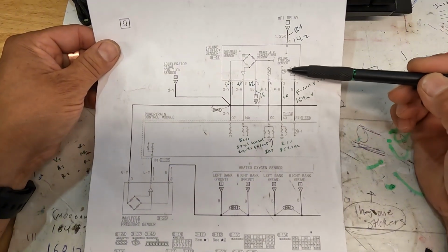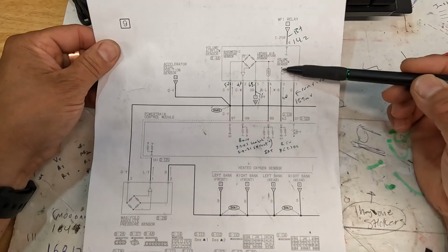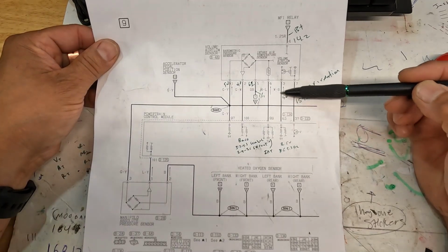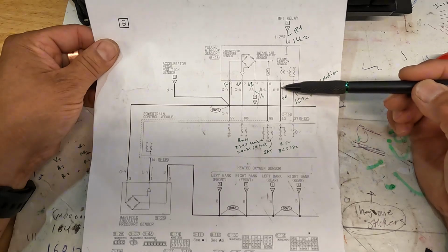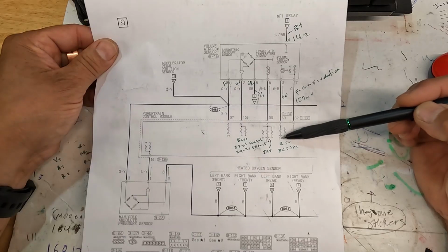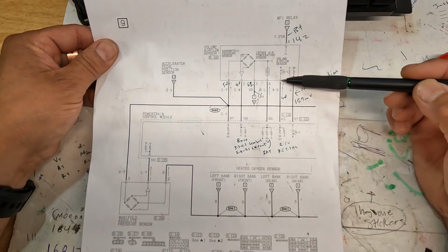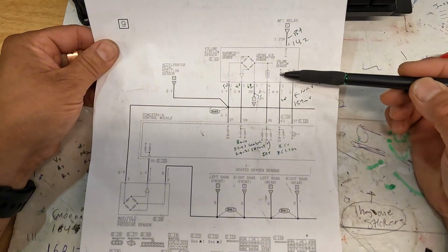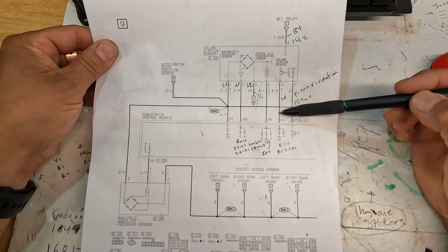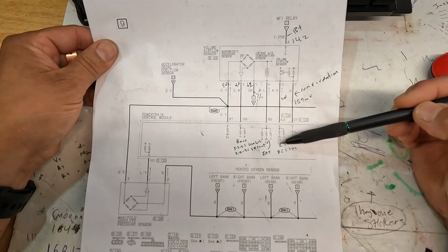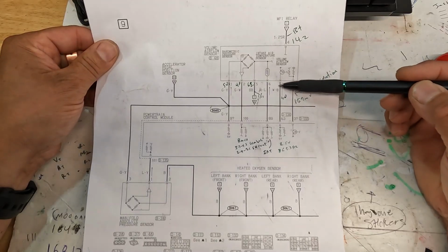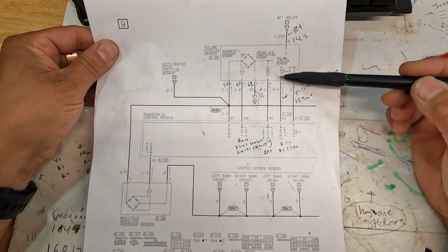This wire should be cycling on and off based on this transistor, so we should have gotten like 2.5 volts on there. So there's no signal going on in this wire, but we do have the 5 volts coming from the computer that are making it to the mass airflow sensor. It's just that the mass airflow sensor is not generating a signal, which lets us know that this wire is okay between the sensor and the computer. It's not shorted to ground, or it's not an open circuit. So we're dividing and conquering this circuit just based on that knowledge.